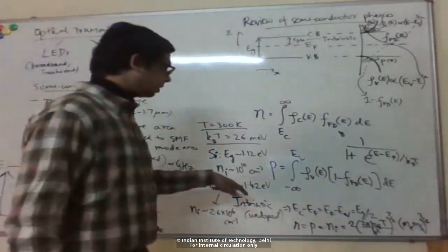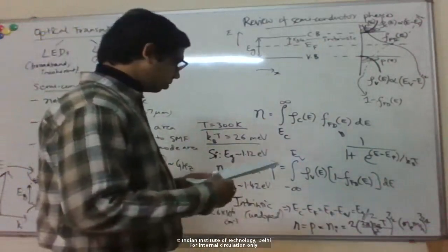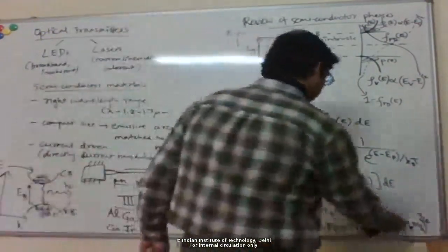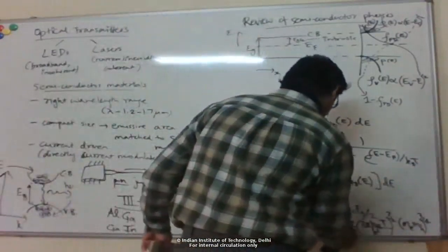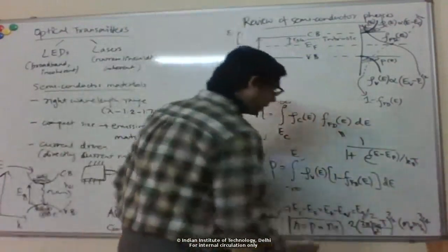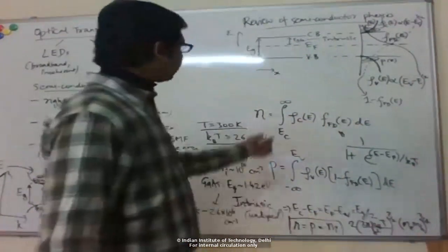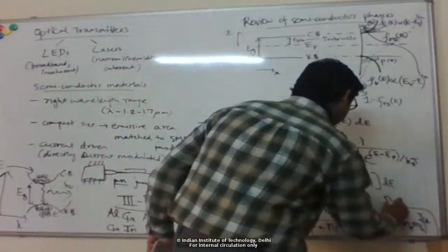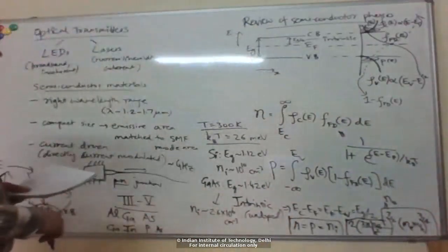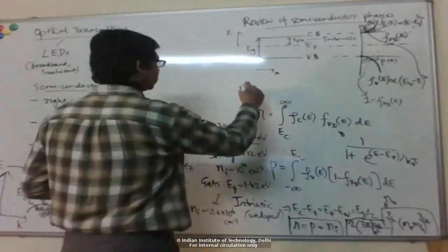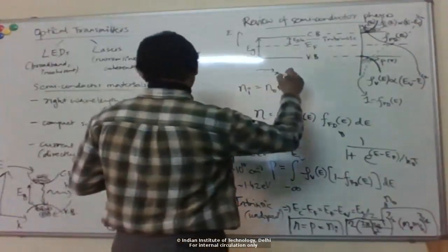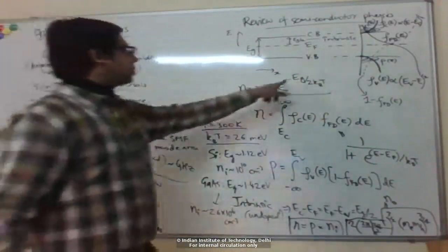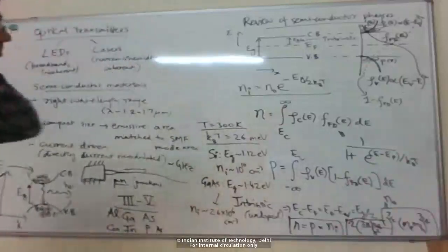Okay, and mainly, you can see that it's coming from, I missed out a factor here, right? So it's this constant times. Of course, it has to depend on band gap also, right? The intrinsic concentration depends on the band gap. I forgot to mention that here. So this constant is some N naught, and Ni, the intrinsic concentration, is this N naught times exponential of minus the band gap divided by the thermal energy.